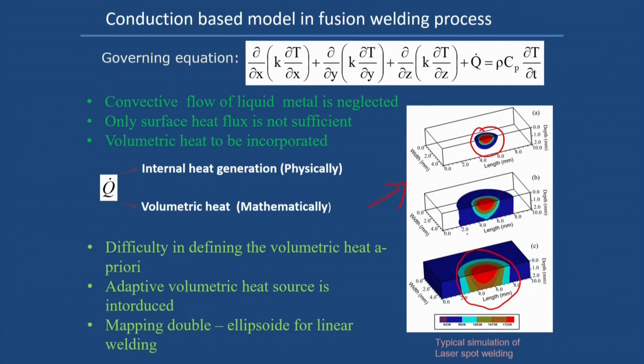At the same time, we can estimate the heat affected zone by the different colors. In this picture, the red color represents the weld pool dimension, that is, the molten state of the workpiece material, and the other colors indicate where solid state phase transformation happens, depending on the temperature distribution. That kind of information we can also find from the simulation, and it resembles the actual welding process.